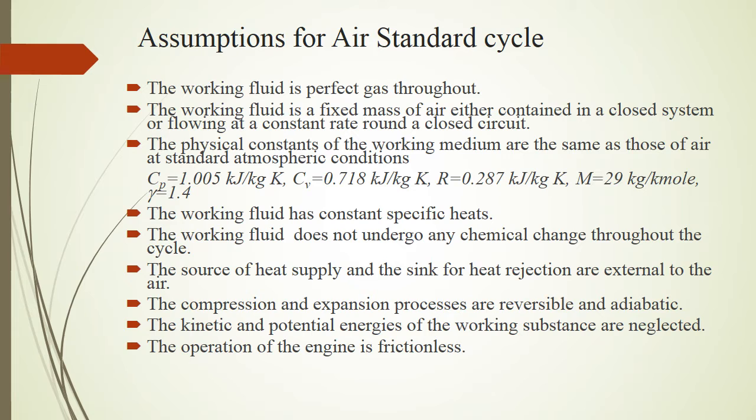the surroundings. But strictly speaking, the IC engine does not operate on a thermodynamic cycle as it involves an open system with new substance or new fluid continuously brought in at one set of conditions, that is at the suction conditions, and released at other conditions, that is, the exhaust gases thrown outside. So the conditions are different for both cases, suction and exhaust.